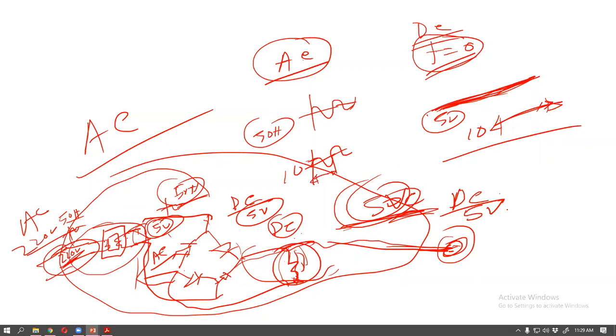It only steps down. If you need 10 volt, it converts to 10 volt. If you need 5 volt, it converts to 5 volt. This 5 volt is AC. Then to convert this AC to DC, a rectifier circuit and filter circuit must be used. Then the pure DC is connected to our mobile charger. Okay, all are clear.